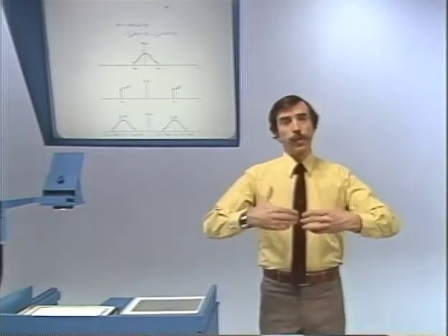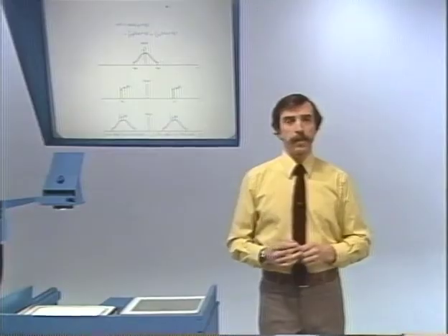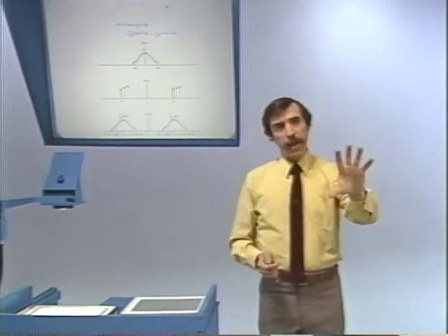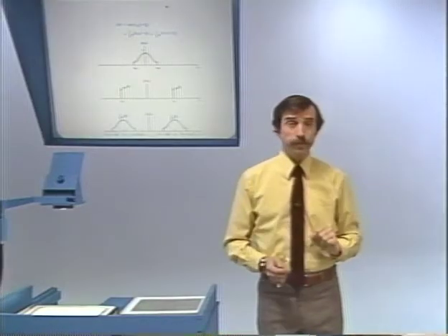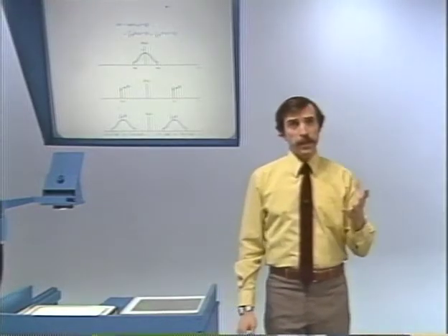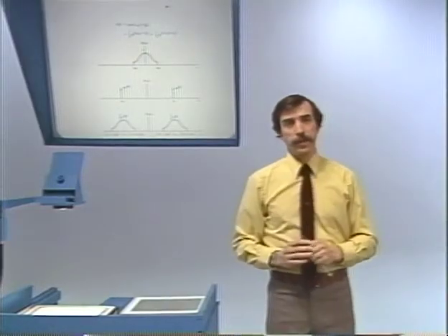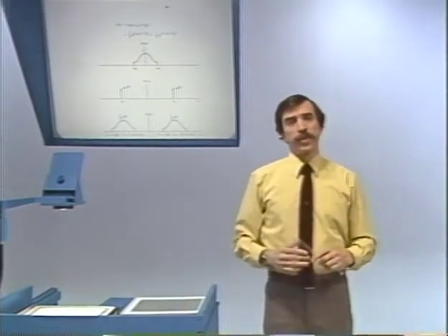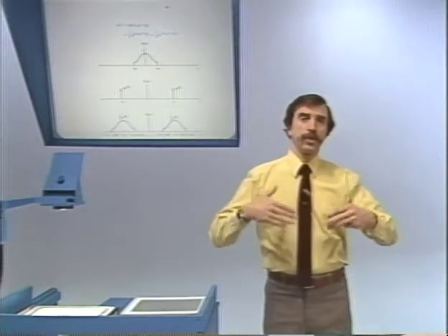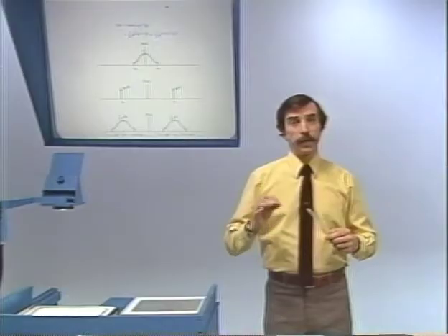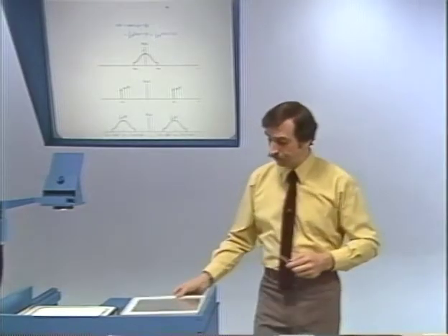And now if we want to get the original signal back again, what we would like to do somehow is move that spectrum back down to the origin. In the case of a complex exponential, that was easy to do. We had shifted one up, we just shifted back down. Let's see what happens if we attempt to demodulate by again multiplying by the same sinusoidal carrier.